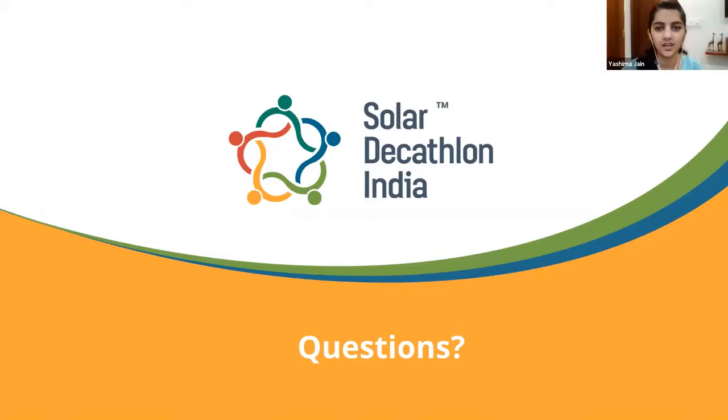Great. Okay. Next question. Why do we need to do the load calculations for a particular time in a day rather than for the whole day? So the concept is that theoretically, there's one hour of the whole year where the maximum cooling is occurring. That one hour of the year is when everybody's in the building, the temperature outside is maximum, and the sun angle is exactly right to get maximum sun into the window.